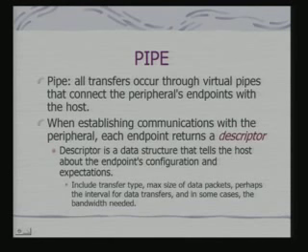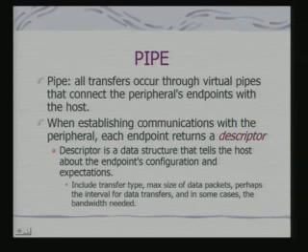This data structure has a specification for transfer type. There are different types of data transfer which can take place on the USB bus, so it indicates the transfer type. It also indicates the maximum size of data packets, because that would depend upon the capability of the client device which is getting connected to the bus.